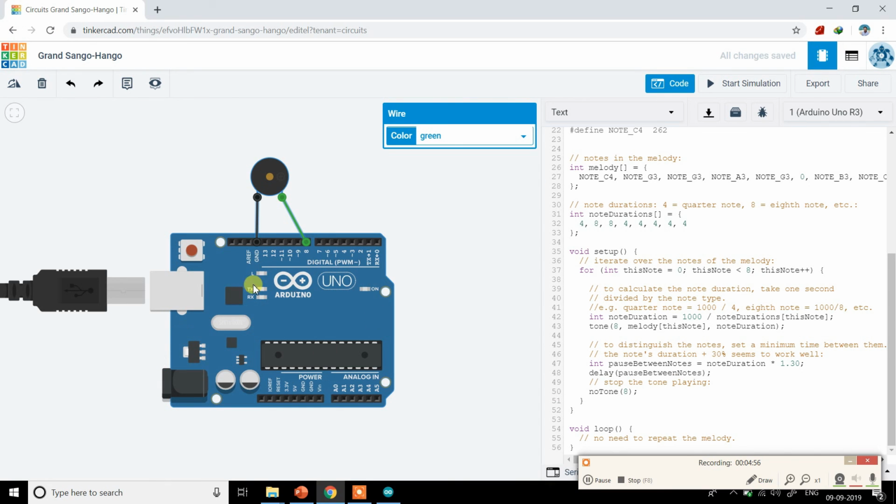There was nothing much to learn about in the interfacing. You just have to take the buzzer, find out the appropriate anode and cathode or positive and negative wires, and connect it with Arduino. So experiment with it and listen to the audio generated.